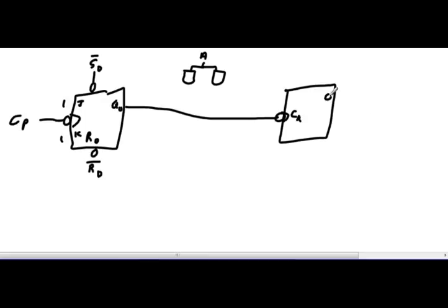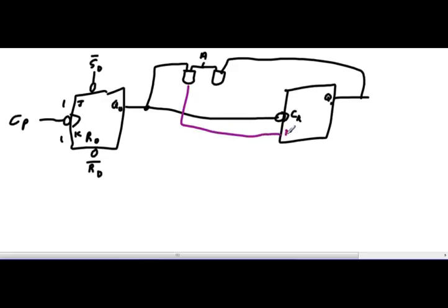All right, I got that. Okay, I'm going to take Q1, and I'm going to bring him into there. And I'm going to take Q0, and I'm going to bring him into there. And then I'm going to take that AND gate into the K, and the other AND gate into the J. And I'm going to put a 1 on the reset guy. And we're going to put kind of an SD naught guy sitting there. Okay, so picture is fine.